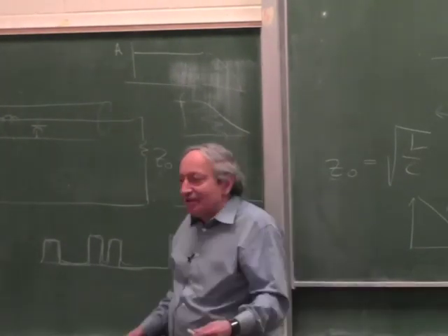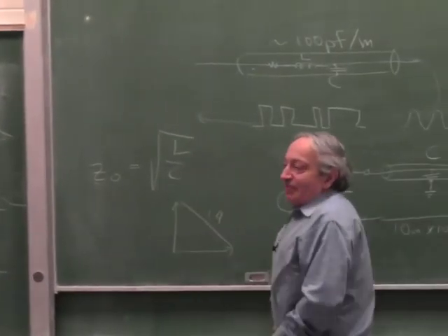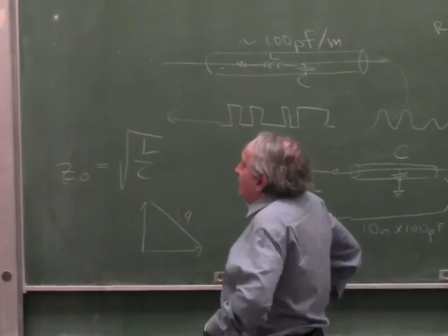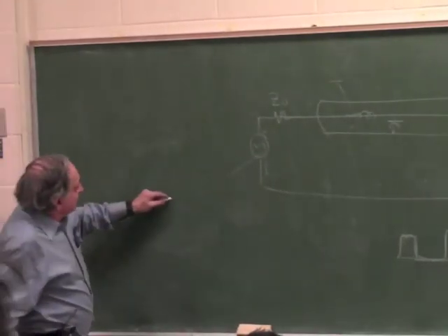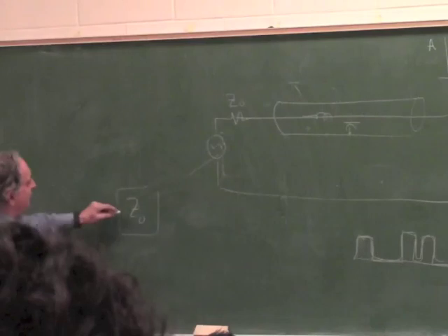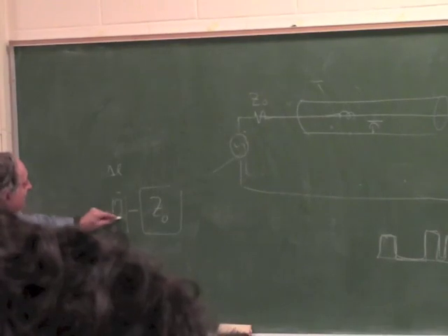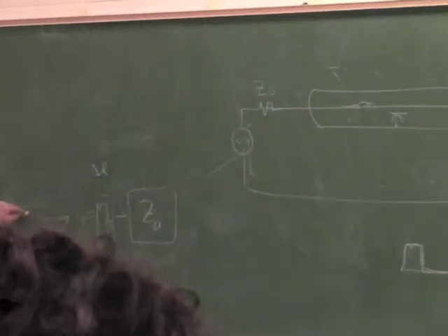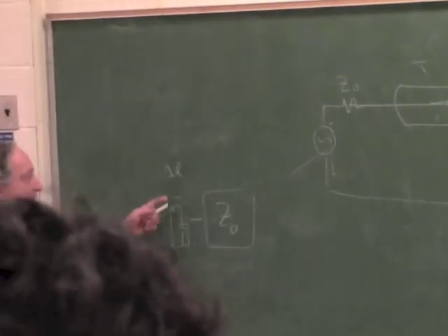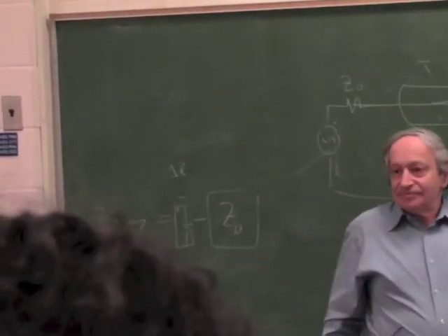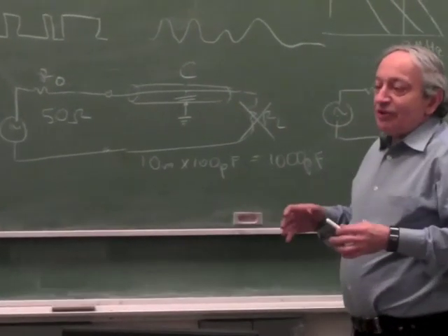Okay? And because of lack of time, I didn't prove to you that Z0 equals this, but if you want to prove it to yourself, you do what Heaviside did, as I reminded you. If you have a transmission line which has a Z0, and you add a little section, delta L, so you add delta C and delta L, when you look inside, it should still be Z0. Then you write the equation, and then you make delta L go to 0, and then you get this. So if you're really curious, you can convince yourself with that. So, whenever you put a piece of cable,